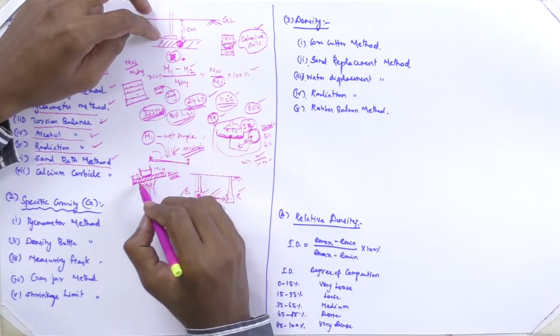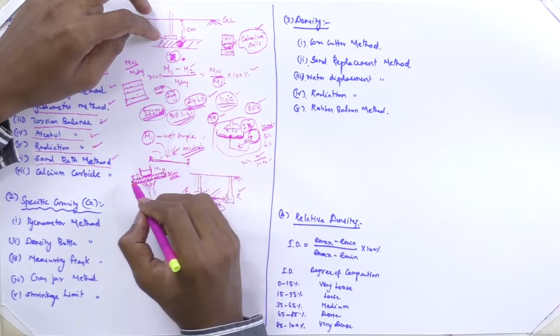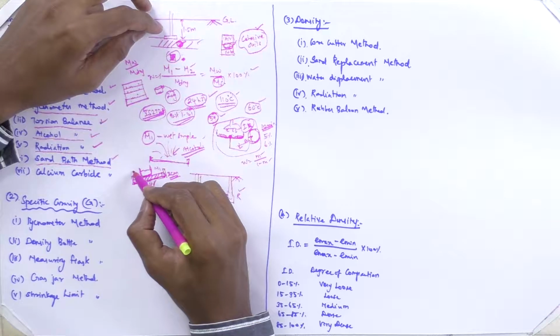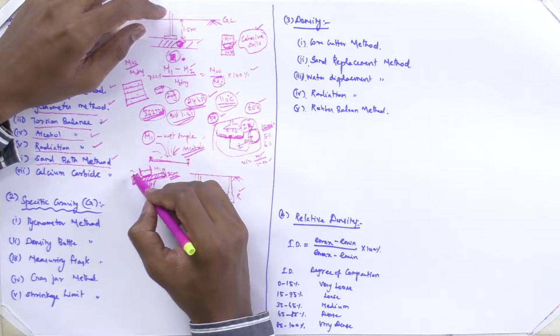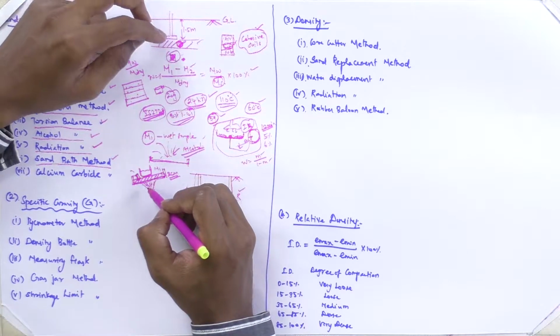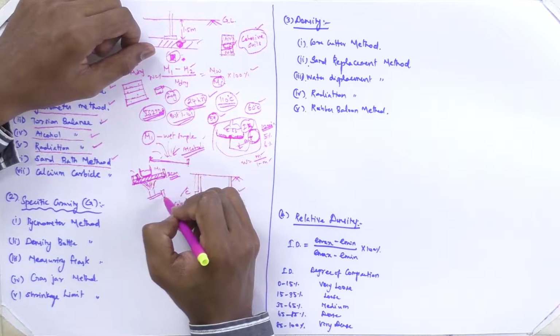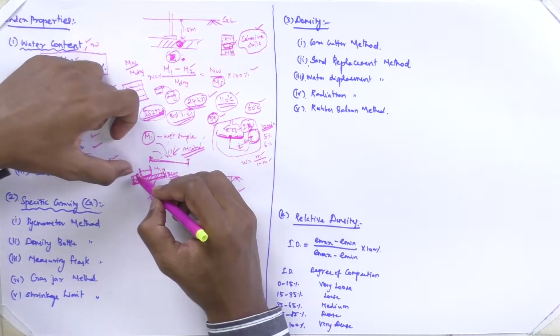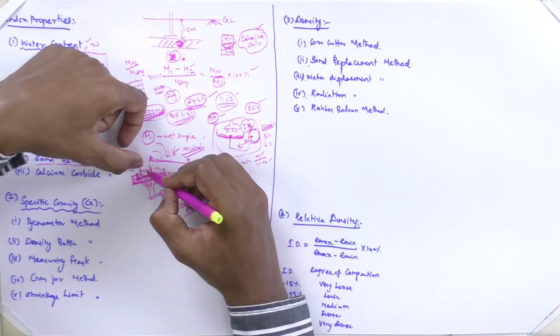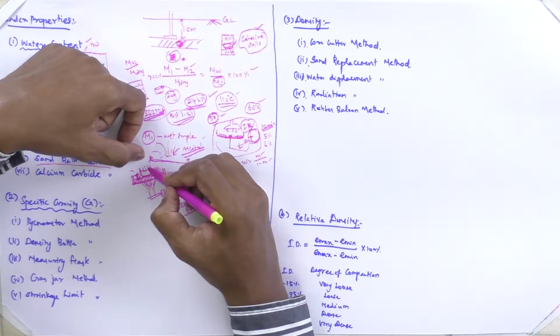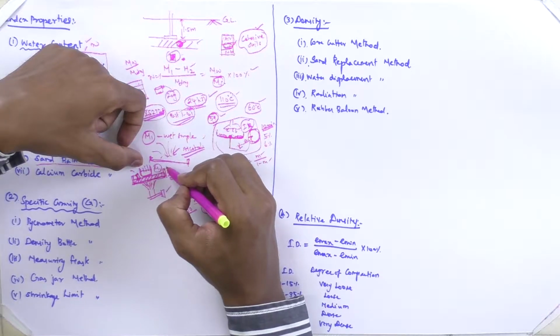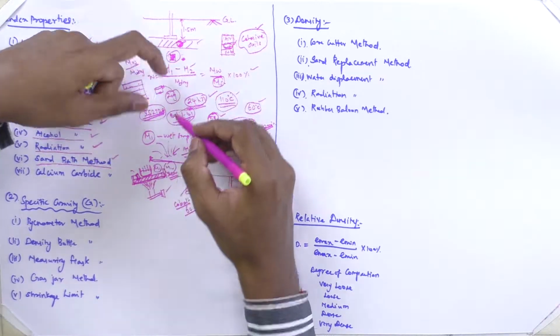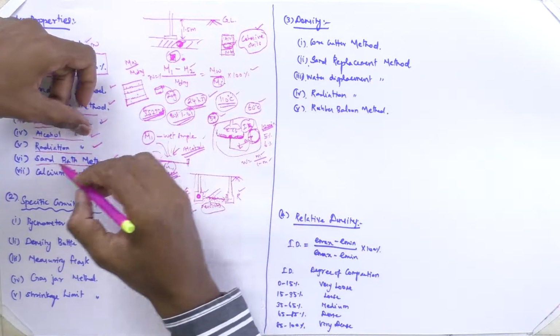If you start heating the tray, that is a steel tray, the temperature has to be maintained at a limit where this paper should not turn brown. That is the heat you have to control here. So this is a controlled setup, and this white paper should not turn brown as it gets heated. Because of this heat, it will lose the moisture, which gets evaporated. So at the end you will be getting M2. So M1 minus M2, as explained the same way, gives you the moisture content value.